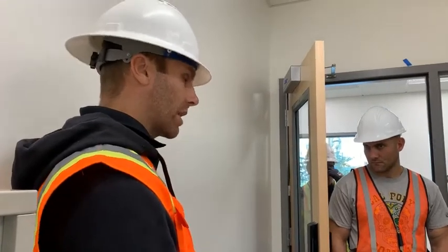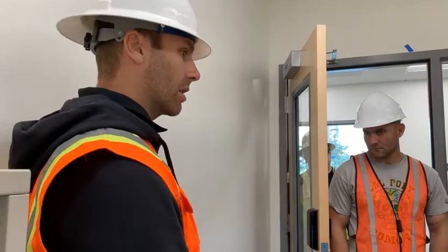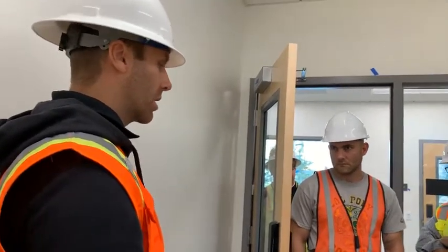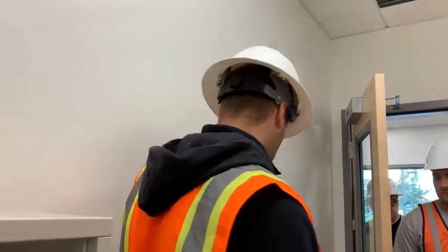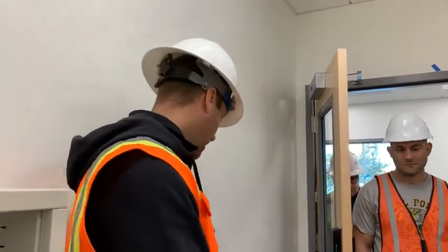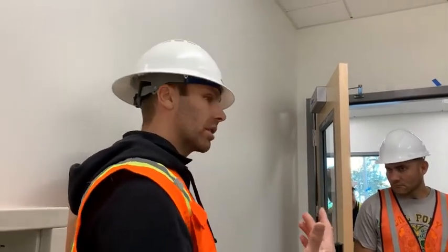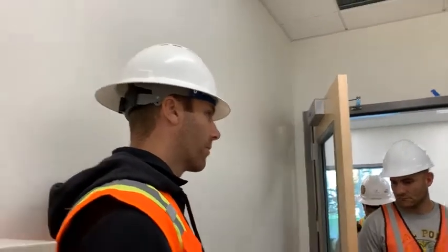Second are the receptacle relays. Teach them that where they say controlled, why that is and what that's doing, and that if you plug in your tower to it, you're gonna be turning off your tower all the time. So the intent is something like a fan, a lamp, your computer monitor. Heater. Yeah, a heater, any of that type of stuff. Yeah, it could be plugged into the receptacle relay. They leave it on, it's not gonna matter, it's gonna turn off with the sensor. Your actual CPU would be plugged into a normal relay or a normal uncontrolled outlet, okay?